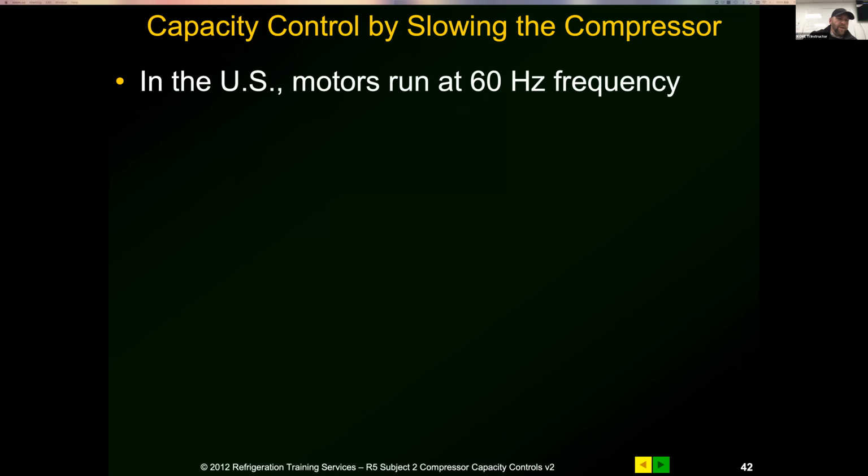Most of the time, you'll see the controllers just use an analog output to send the signal to the VFD to ramp it up and down. Based on the analog input that the VFD receives from the controller, it starts to adjust. So it's not a very finite adjustment. It's very broad, but it works. That's what you'll see out there now. But if you get an Emerson drive and an Emerson controller, they're going to have a program in that controller to drive very effectively and very efficiently.